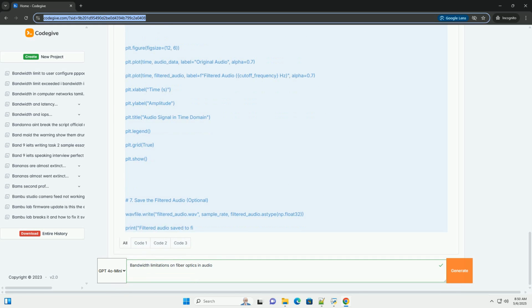Use single-mode fiber whenever possible. Use single-mode fiber to minimize modal dispersion, especially for longer distances.